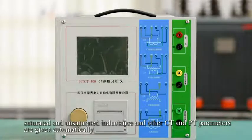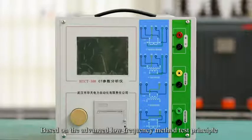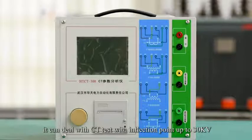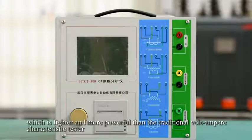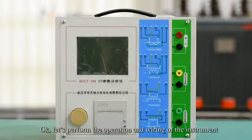given automatically. Based on the advanced low-frequency measurement principle, it can test CTs with inflection points up to 30 kV. This instrument adopts the principle of frequency conversion, which is lighter and more powerful than the traditional volt-ampere characteristic tester, and has more powerful functions.